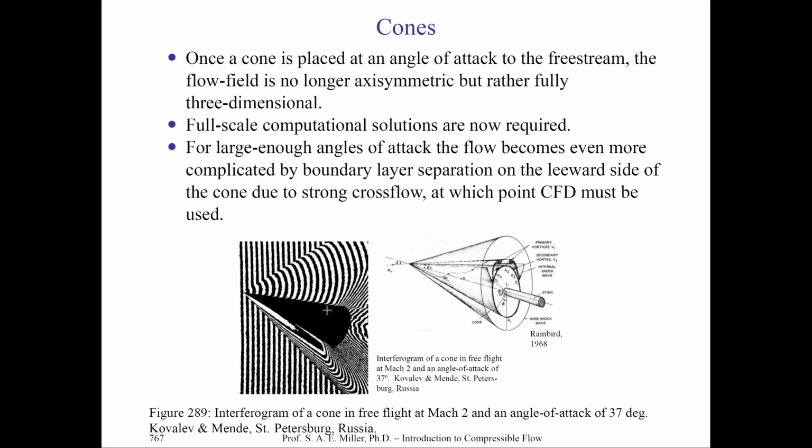You can then see there's a boundary layer on both sides, and look at the strong distortion of the zebra striping, which corresponds to the density gradients' effect with bending of light below the cone, right there. Up top you can see hidden in the flow and zebra striping, and we would not know about it from this particular experiment, these particular vorticity roll-ups. This is a case where of course the experiment has not shown all the flow physics.